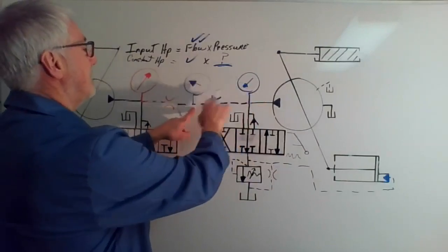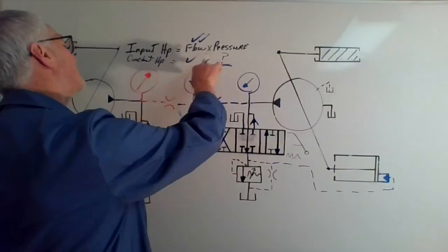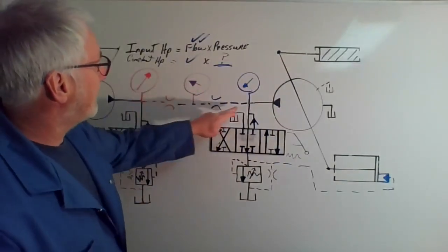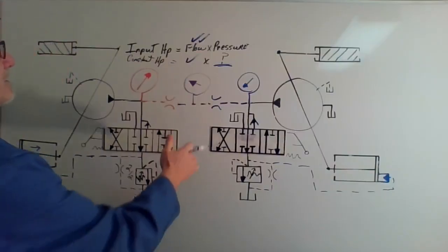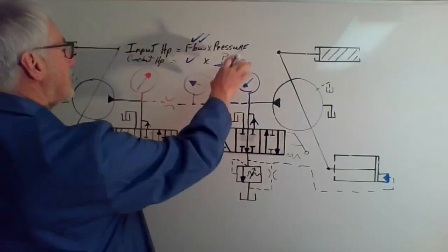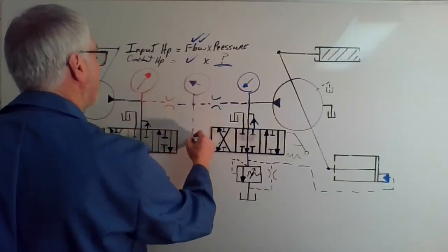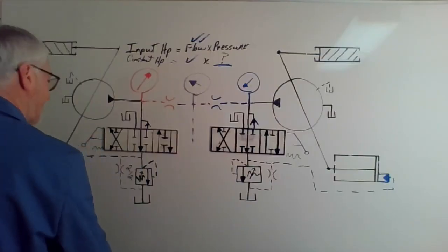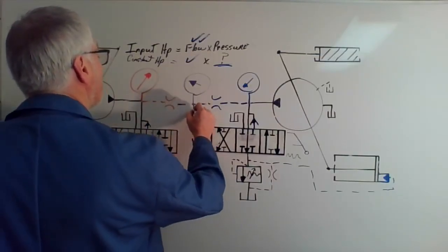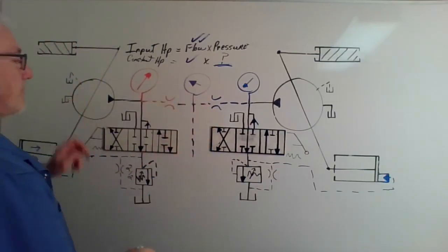And this is lower, and even this side might be trying to feed that way, but I certainly can't put a lower pressure into a higher pressure. So you could have a little bit of transfer trying to drop that way as well. I want to be clear that this is just an orifice passage. If there's oil flowing back and forth, it's only to register a pressure, and I'm going to sense that pressure right here in the middle, and I'm going to take that pressure and do something with it. What I'm going to do with it is hydraulically try to control these swash plate angles.